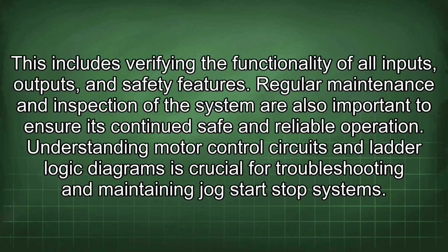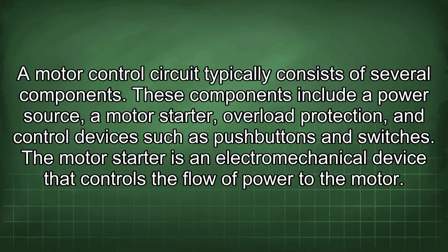Understanding motor control circuits and ladder logic diagrams is crucial for troubleshooting and maintaining jog start-stop systems. A motor control circuit typically consists of several components. These components include a power source, a motor starter, overload protection, and control devices such as push buttons and switches.